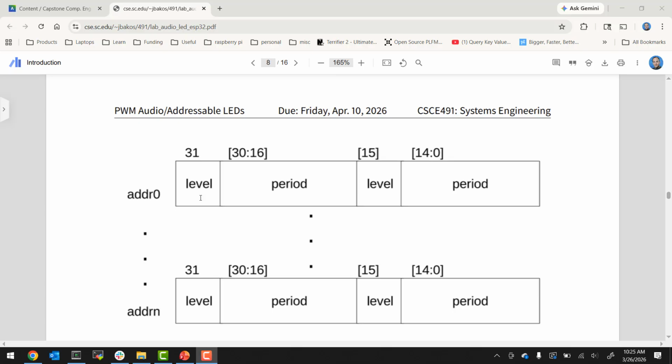That's the problem. If you had more entries in this RAM, you could program all the colors for all 100 LEDs. If you had 2,400 entries in this RAM, you could do it all in one shot. That would be awesome. You could literally just write this array once and send everything out, and all the LEDs would get programmed, right?